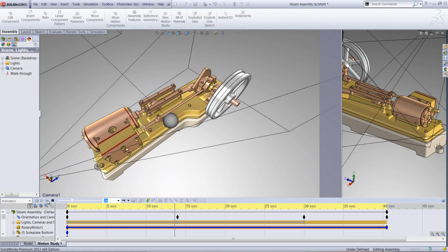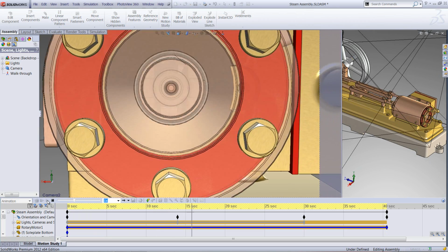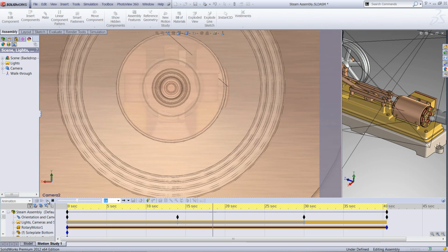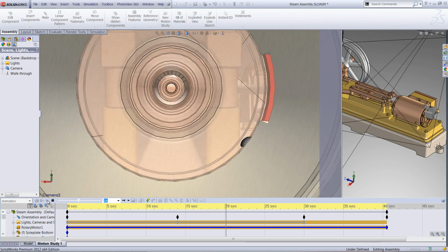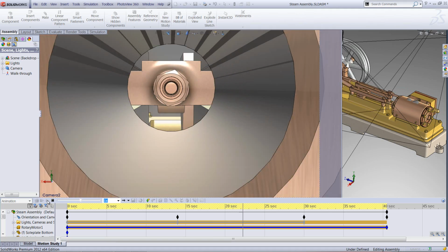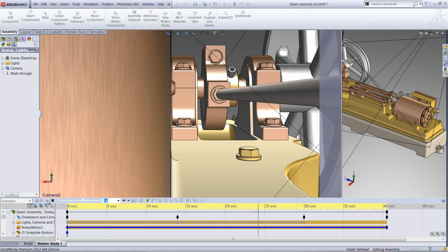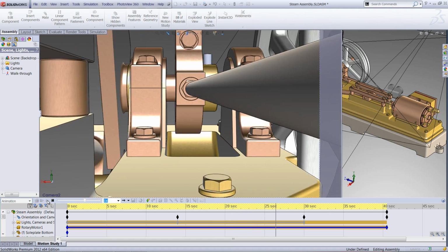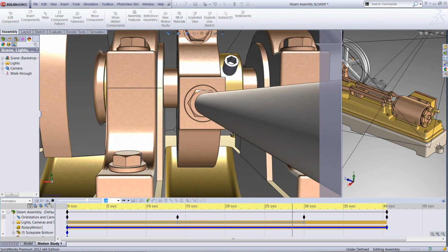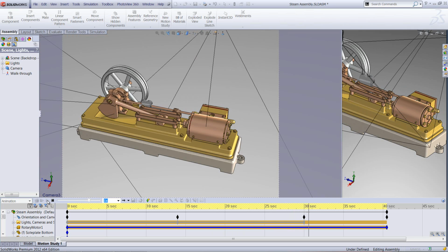At 14 seconds, it's going to snap to the second camera. It's going to move through those transparent components that we've specified. Then follow along that path towards the end of the assembly, and finally at 30 seconds to 40 seconds we've got an isometric view of the component slowing down. So the interpolation mode was to ease into that 0 RPM, and there we have it. It stops at 40 seconds.